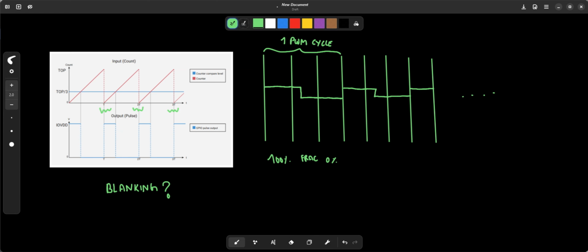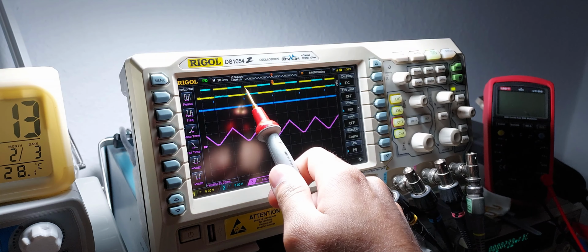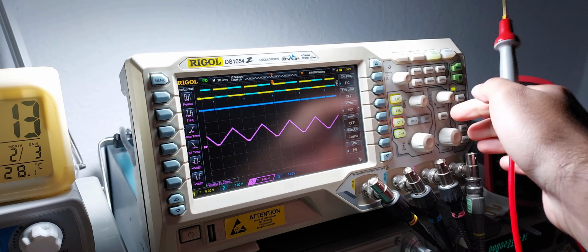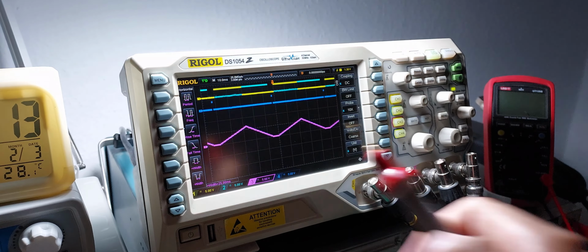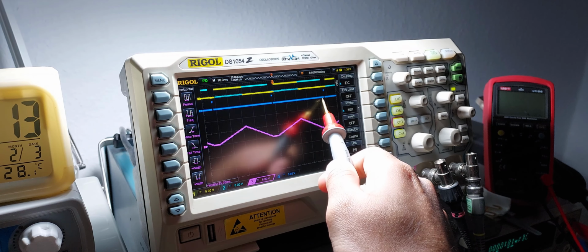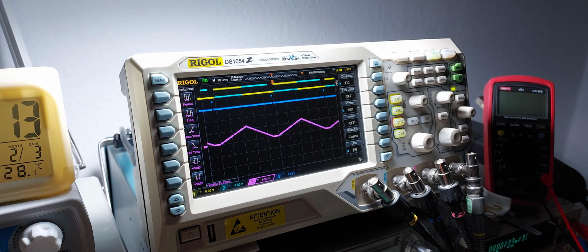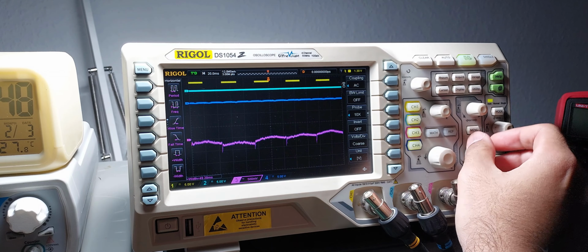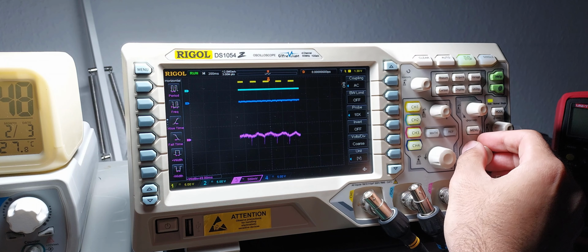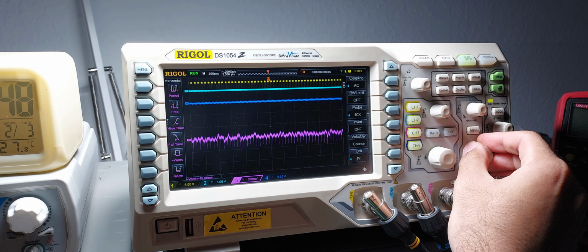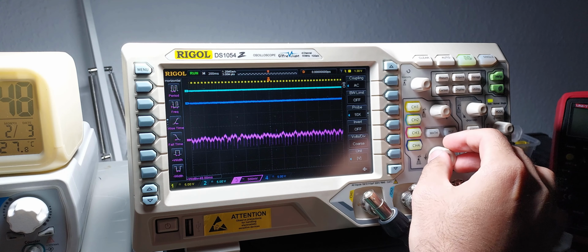The biggest advantage of this method is that we are freed from the limitation of the counter wrap value, which is around 65,000 given the 16-bit counter, making an arbitrary resolution possible, within reason of course. I was pleasantly surprised to see that this scheme worked as intended, with each reference being turned on in a complementary fashion, with a blanking period where the integrator is sampled. This led to the lowest measured noise for this project, which was around 20 microvolts peak to peak after decreasing the width of the sampling pulse even more.